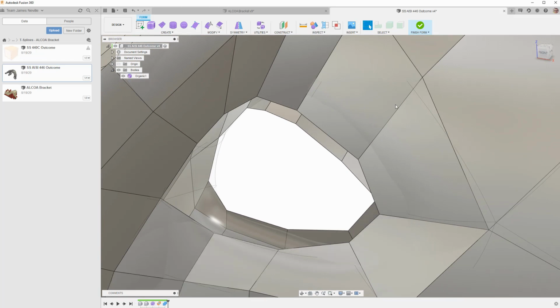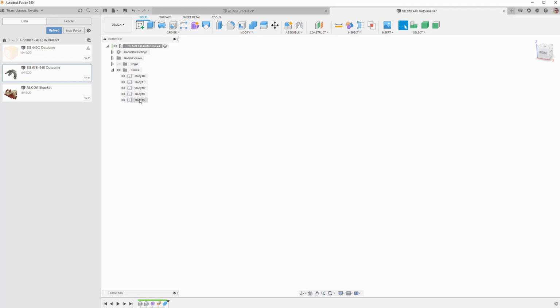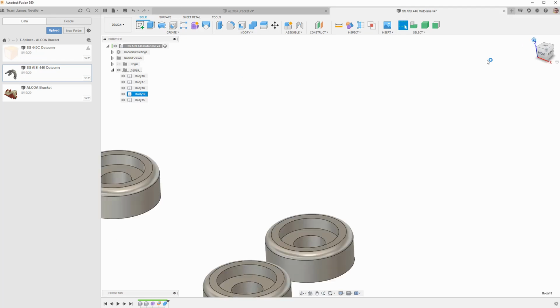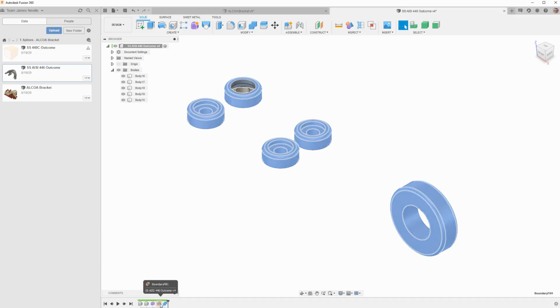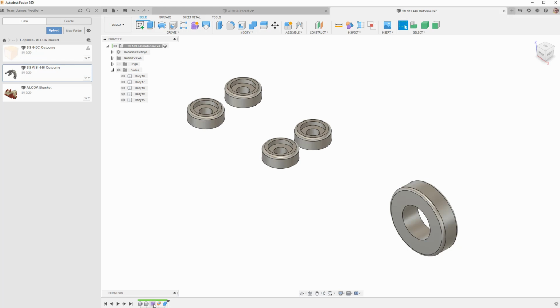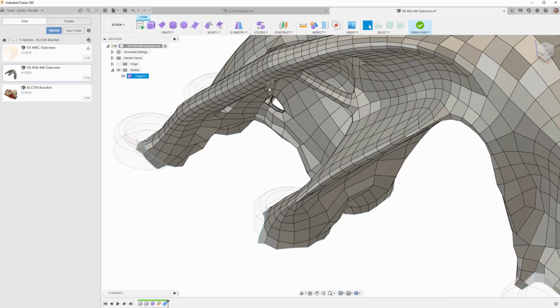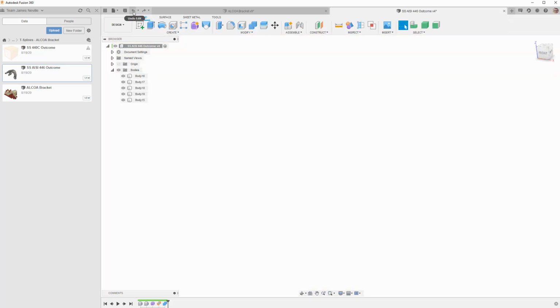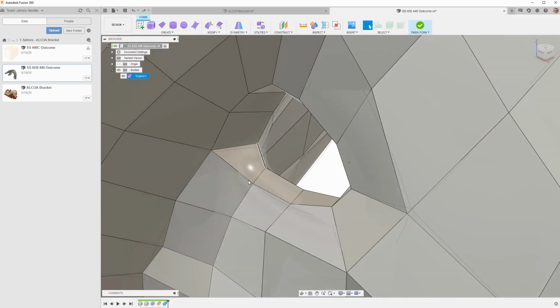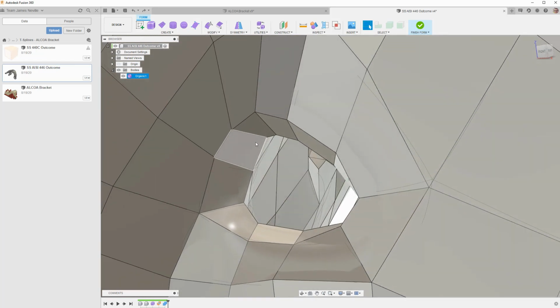If I was to exit out of this form environment, there won't be any body, right? There's nothing here. I just have my geometry because the boundary fill is no longer able to do its work because that's an open surface. Let's go back and undo that. So instead of just deleting, there's an elegant way to do this.